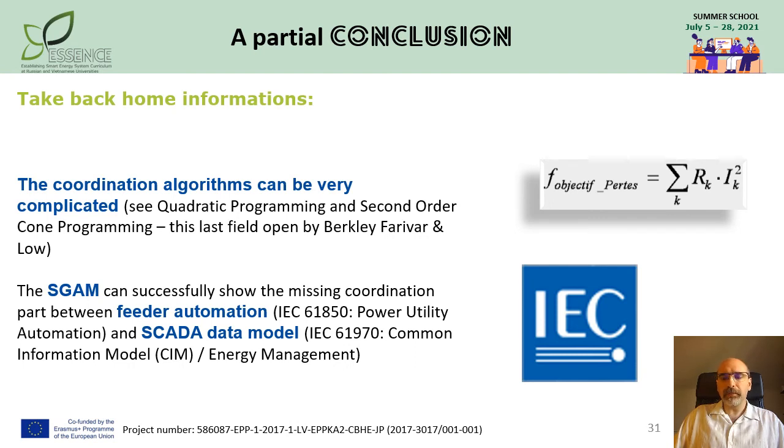Let's now jump to the partial conclusion of this part and take back home information I want you to keep in mind. At first, a coordination algorithm can be very complicated, and you can rely on some very advanced optimization methodologies, such as quadratic programming or second-order cone programming, those fields that were opened by Farivar and Low a few years ago, colleagues from Berkeley, that are allowing you to reduce, for instance, losses while still trying to apply some linearization scheme to have optimization very efficient, even if you have a problem that is non-polynomial difficult,